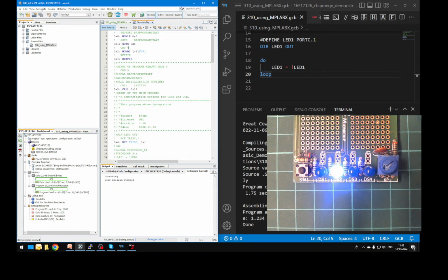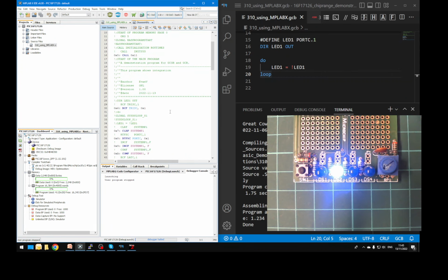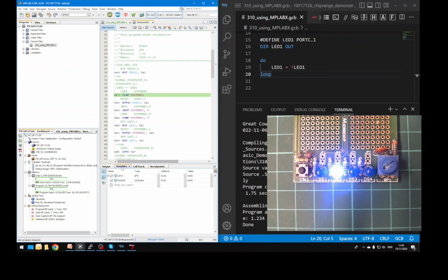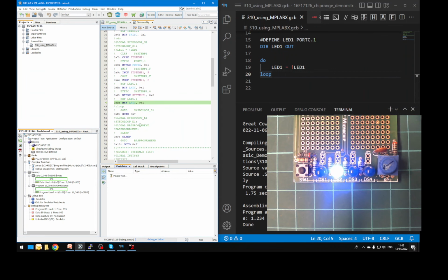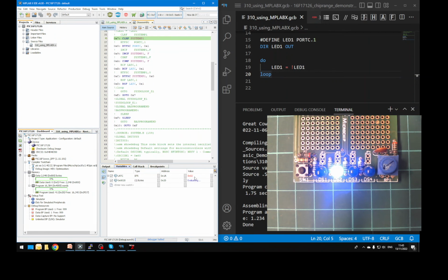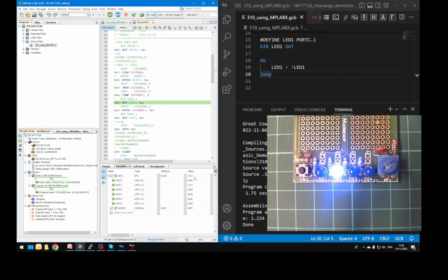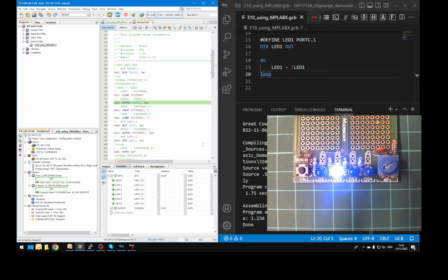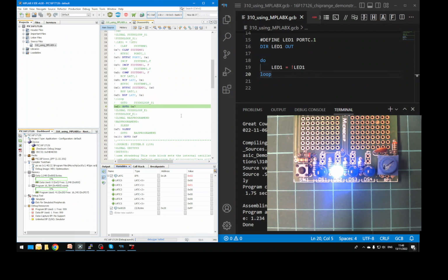And now we are in our source program, but this time when we walk the program, I'm going to put a debug halt here. Here we go. If we look at our variables now, you will see that the LATC values are accordingly changed because now we're setting up bit 1, not bit 0. C.0 versus C.1. So what we're getting here is quite sophisticated operations in terms of the debugger.